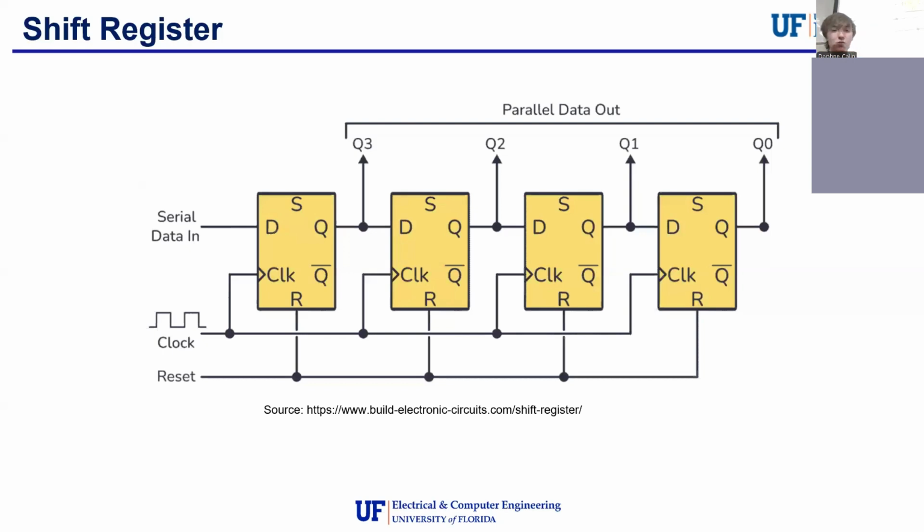Okay. So this is a shift register, right? I don't know if you guys learned this in class, but it's an array of D flip-flops that basically allows us to have serial communication. You'll use this in micro P if you take it, but you do also need to know it for digital logic.